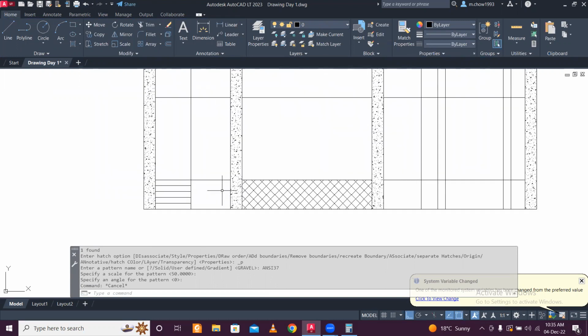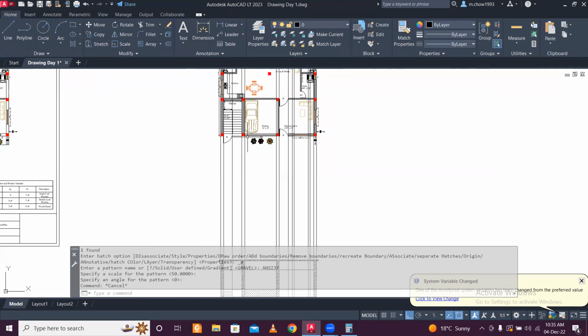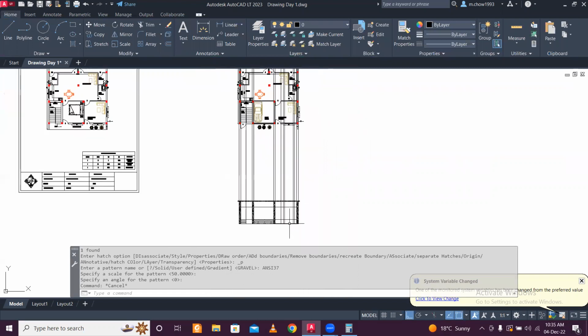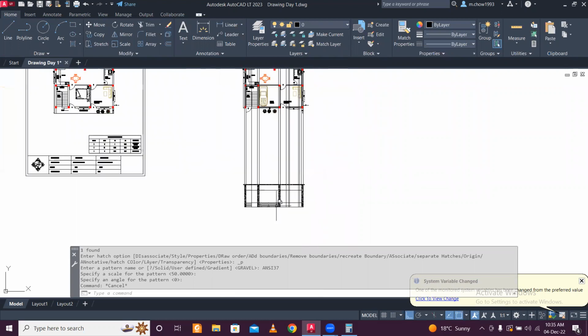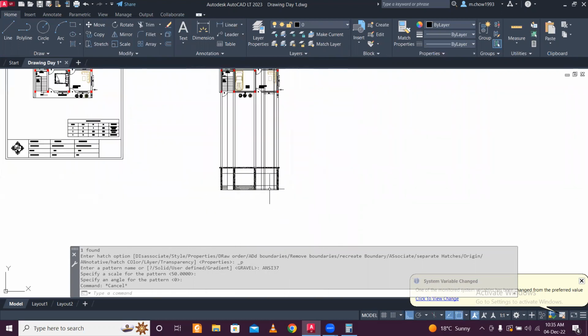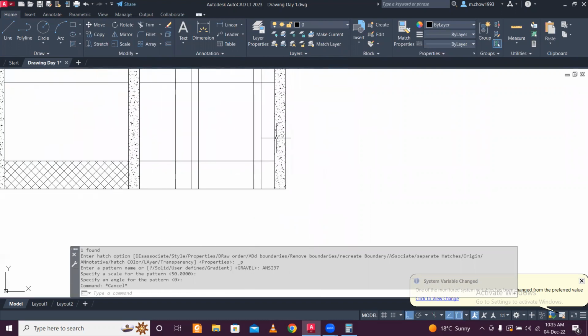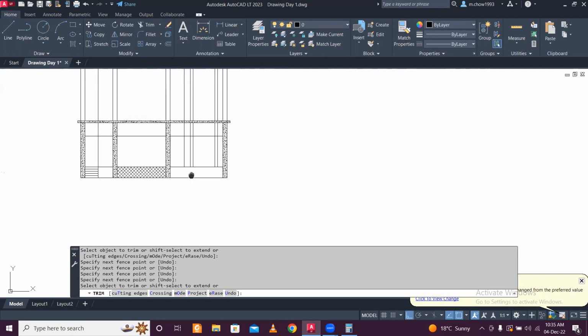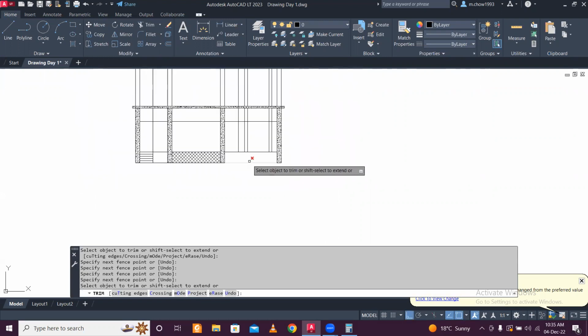That represents the ramp, and the remaining part is the elevation. This is the elevation, obviously. This will be masonry work. So we'll do the masonry here, and here. Okay, everything will be masonry. This portion also. So let's just use the trim. TR, double enter in the older version, here single enter in the new version. Trim it.